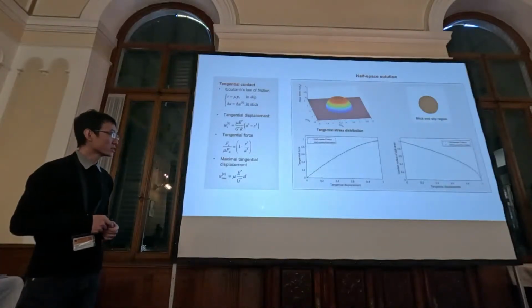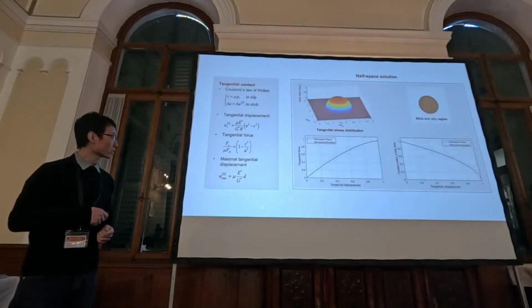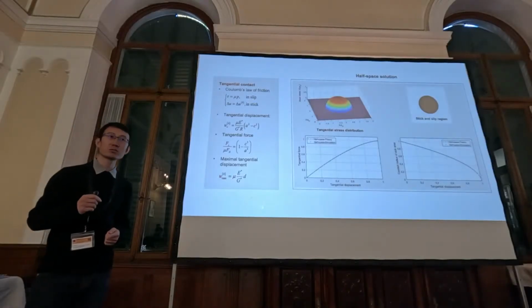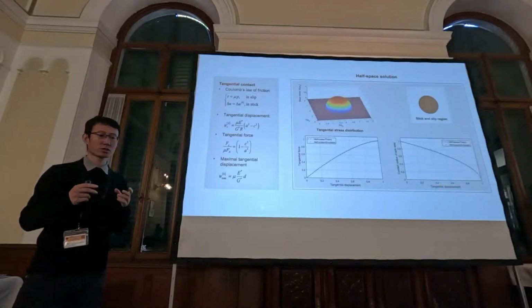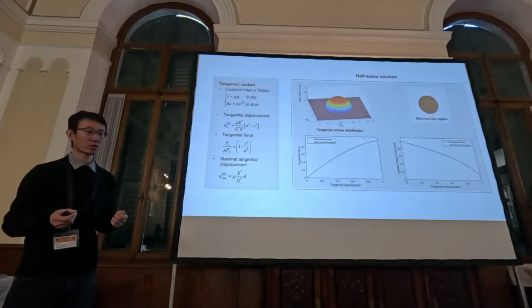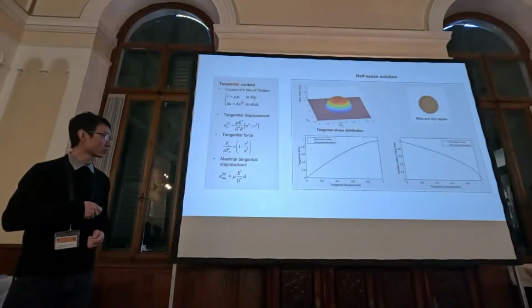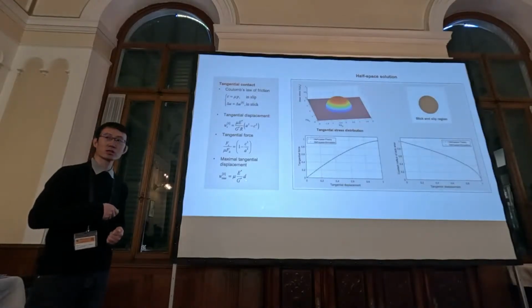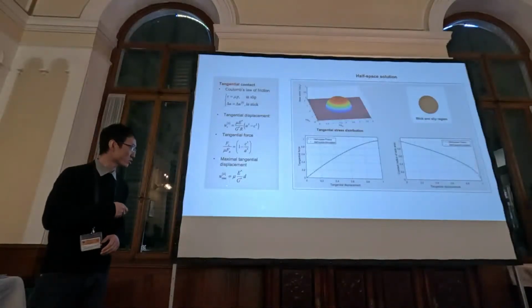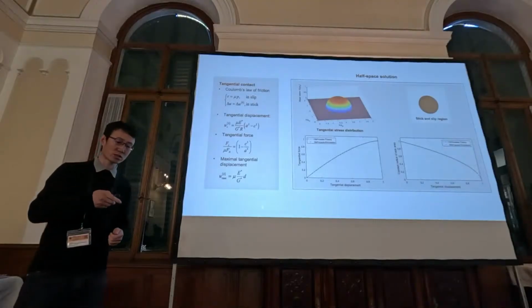And here I would like to mention this result is for the maximal tangential displacement until the gross slip. In the classic half space case, this maximal tangential force is independent of the indenter geometry, whether you have a sphere or cone or some rough surface. It depends only on the friction coefficient, the material, and the indentation depth. I think this is also what Professor Molinari questioned in the last session.